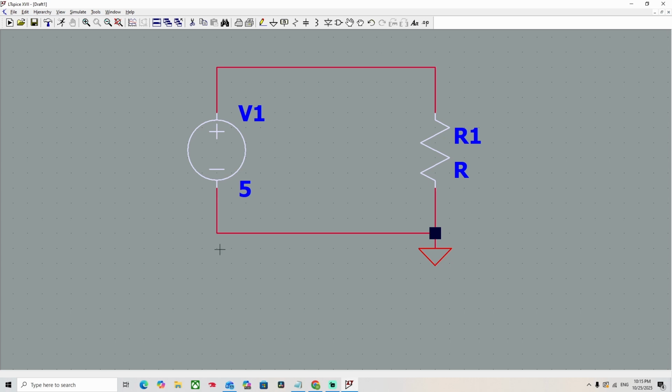Let's say that we start at the lower left-hand corner. The equation would be -5 because we see a negative voltage first, and it's 5 volts, so we'll call it -5, or you could just leave it as -V1, if we didn't know what this was. Then we keep following the loop here until we meet a resistor.